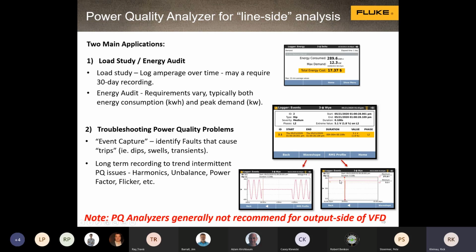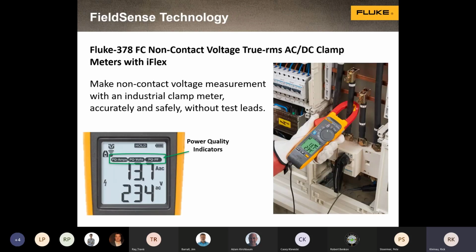If you look at the RMS voltage, what you'd read on a meter, we call that the RMS profile. But if you see it on an oscilloscope, this is what we would call a snapshot of the waveform. So you see where the voltage just disappeared and came back. And depending on the logger, you may or may not have this kind of detail at the bottom. Maybe it's just the digital readout. Speed determines the cost of a logger. There are a lot of little details there.